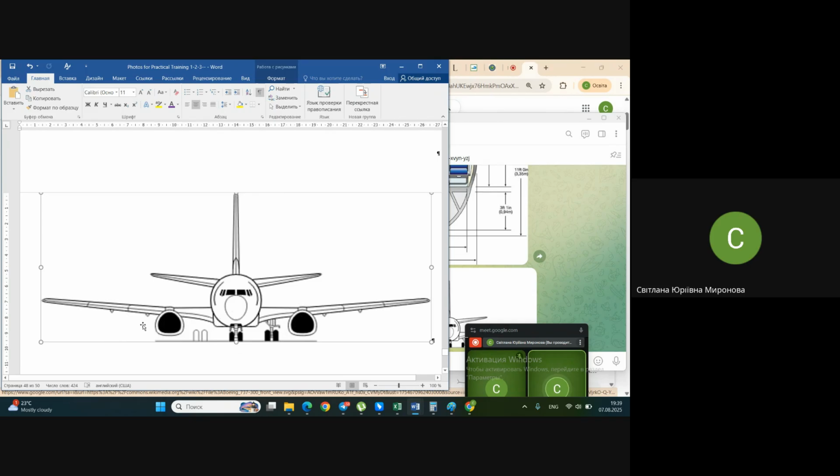Of course, what is the reason for placing engines in such an improper position? I already said, it results in unloading the wing in flight. On the ground, it additionally pulls the wings to the ground, like a heavier wing.